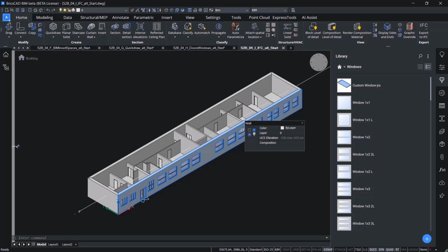And then the second method is more of a direct modeling workflow, but instead of just modeling directly, we're actually using some smart BricsCAD tools like Quick Draw and Quick Wall to quickly lay out the majority of our geometry, and then even using simple manipulation tools like trimming solid that we've introduced in version 23 really helps speed up the process.